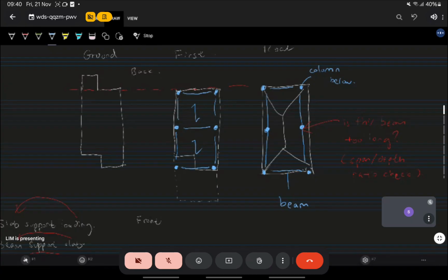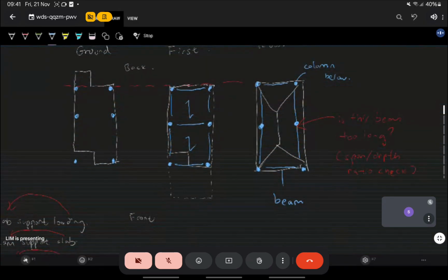Okay. Now, then you copy the column to the floor below again. Then you can do the same thing. And then you show the slab span. Okay, that's it. So now, this is what we call framing a building. Now our building has a frame already. You can actually start designing the beam, slab, and column, if you know how.